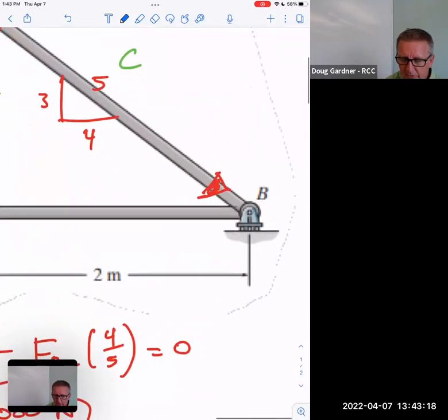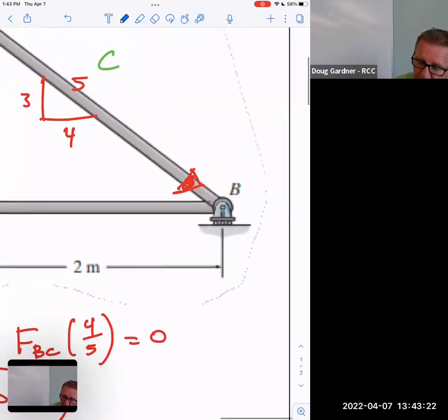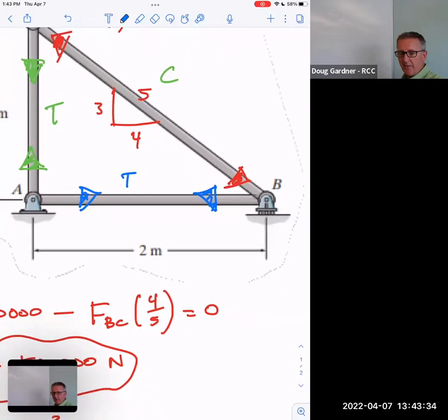So anyway, I'd have to proceed over here, right? In order to get this one, I see, as a result of that pushing downward and at an angle, this is going to have to pull back in this direction. So I can see that this last one is also going to be under tension. As soon as I found that tension number, I could divide by the same area and I'd get my answer for that one too. So then that whole thing would be in balance without too much work to be done.